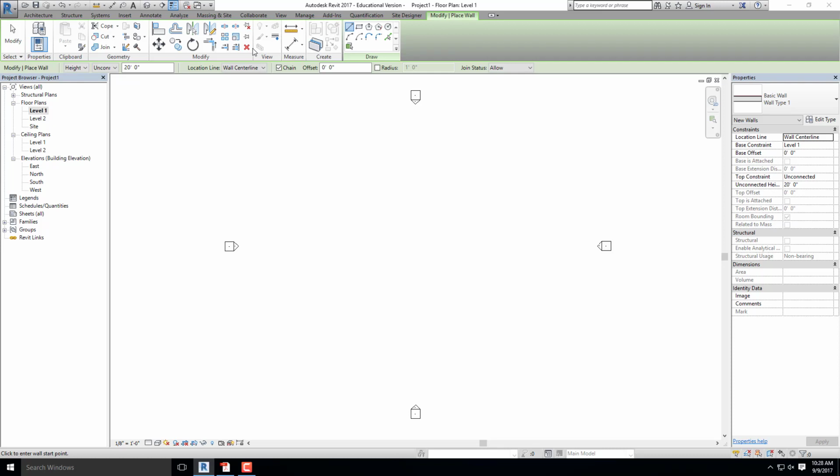Okay. So just curious, why do you think we wouldn't use exterior face of finish? Any ideas? You probably won't know this answer unless you work in construction. But the reason why we actually don't do outside face of finish is if you give a contractor outside face of finish dimensions, I guarantee you're not going to have a wall that's built the dimension that you want, because it just starts to add a mathematical component to it, to where they have to start to think about what the thickness is, and then they figure out what the actual dimension of the stud is, and it adds a whole extra component that it's not always the best to do. So it's better for you to do that math yourself.